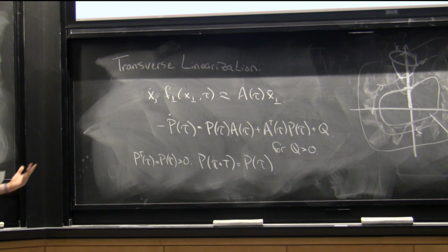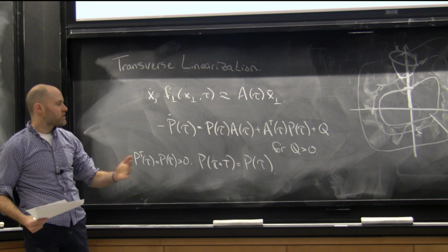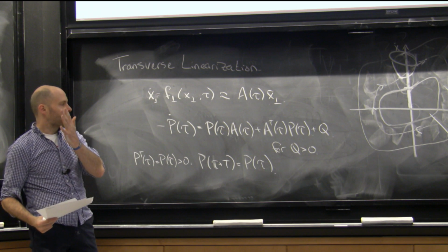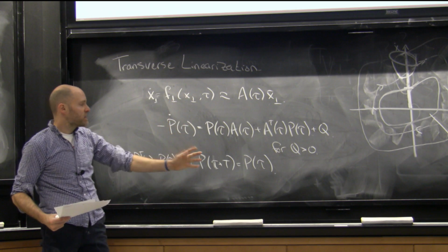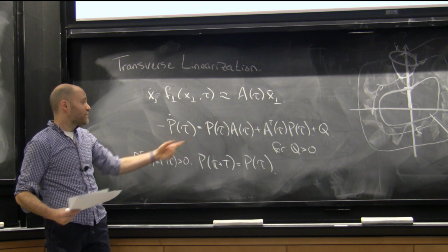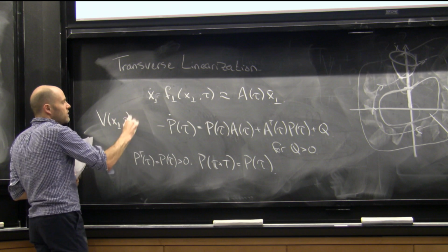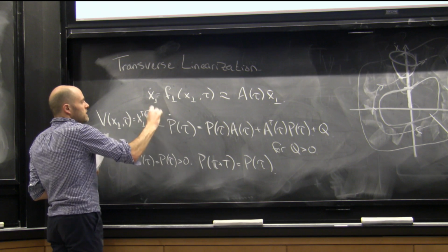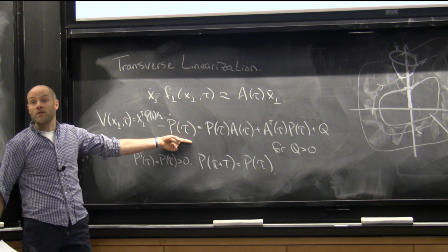Okay, so just like I solved the Riccati equations backwards in time to find LQR solutions, I solved the Lyapunov equations over time to find an initial time-varying Lyapunov candidate. Here in the limit cycle case, or the orbital stability case, I can find an initial quadratic Lyapunov function, right? So this V of x perp, tau is x perp transpose P of tau x perp, and I can do it by solving this equation backwards in time.